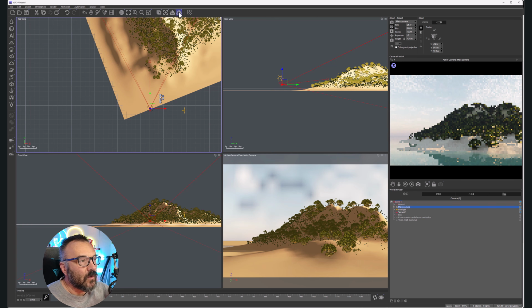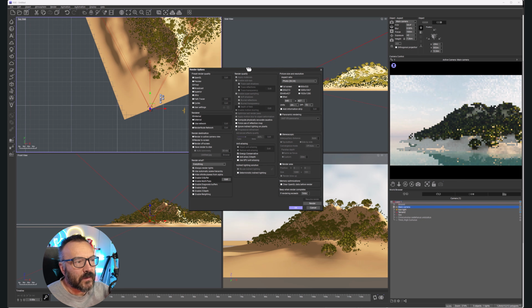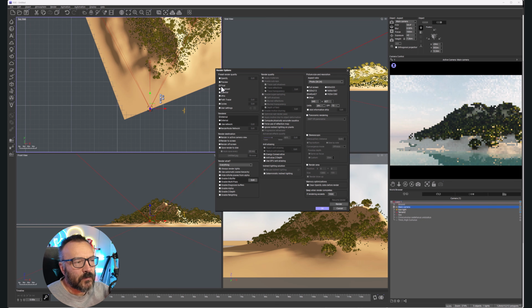To do this, we'll go to the top where it says render, but we're going to right click and open render options. In render options, we want to be sure at least it says final quality as well. We'll have it internal render. We will go render to screen because I want to preview. You can render directly to your hard drive and not see it, but I like this way. And we're also going to render at least HD resolution. You can render with almost any resolution from the presets or just type it in. As well, we can render even panoramic 3D, HDR, or other things.